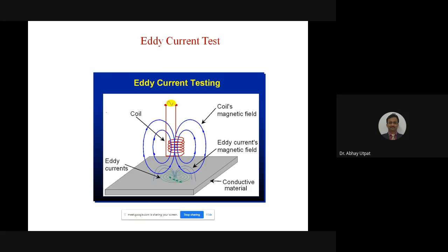Okay. So non-destructive tests are magnetic particle test, only surface crack and subsurface crack up to 6 mm. Used only for parts which can be magnetized. Dye penetrant test is used for the parts which can't be magnetized, but limitation is only surface cracks. Ultrasonic test is used for subsurface cracks, but only it can show the location, but not the shape. And last one is radiography, which is not only showing the position of the crack below surface level, but also shows the actual photograph of the crack.